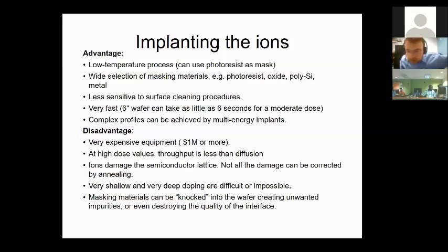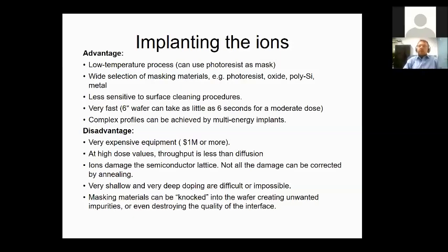Increasing the temperature, you should always keep in mind that there will be thermal expansion going on all the time between your layers. So there should be more and more stress build up. If you have several cascaded layers, temperature increment can be critical. Also keep in mind that you might have polymers in your case, like you will see next week, like photoresist. They will be very susceptible to temperature deviations, and they can't really survive after 200 Celsius or so. So all those are going to be critical.